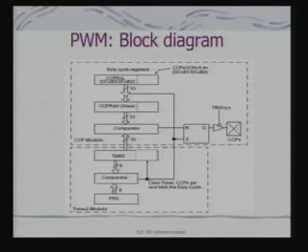So, how does it happen? Let us look at this. Now, what have you got? This is your Timer 2, and this Timer 2 can be compared with this PR2, and by that I can control the period. And using this comparator I can control basically the duty cycle.